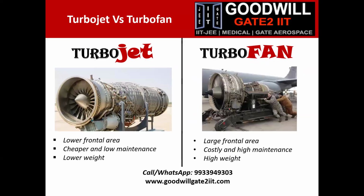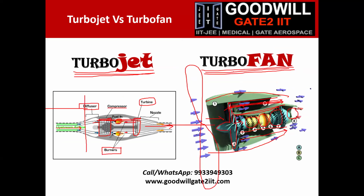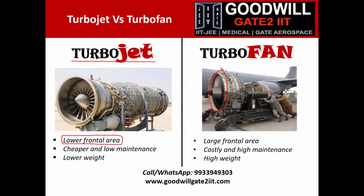Seeing this itself, we can understand a few differences. The turbojet engine is very simple, correct? It has a lower frontal area, the reason being you have not kept a big fan at the start of it. You can see this from the schematic diagram itself. You have to keep a fan, so the frontal area for a turbofan engine is big. Turbofan engines have large frontal areas, whereas turbojet engines have lower frontal areas. That is one major difference.